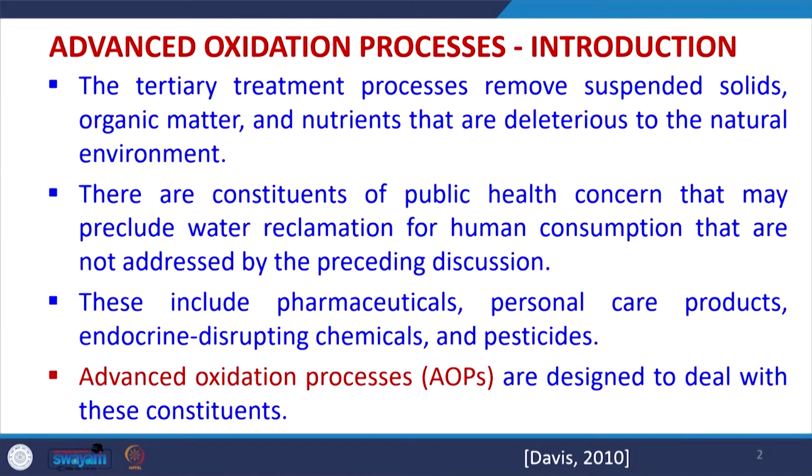Now, the tertiary treatment processes that we have studied till now are the various physico-chemical processes, including aeration, adsorption, ion exchange and membrane processes, etc. They are able to remove the suspended solids, organic matter, nutrients, etc. that are undesirable in any water or wastewater.